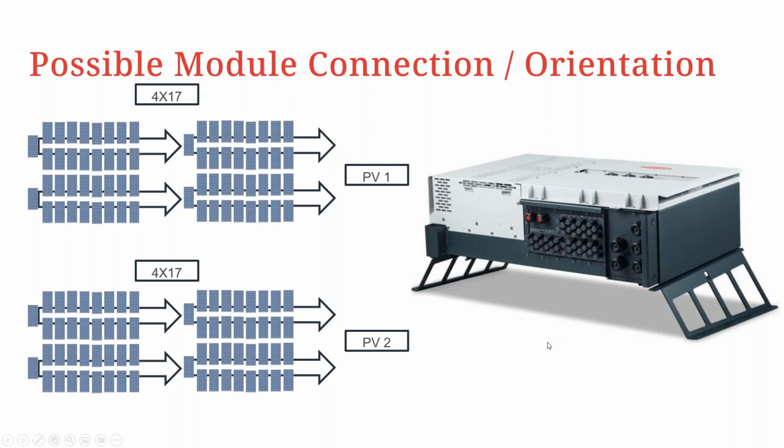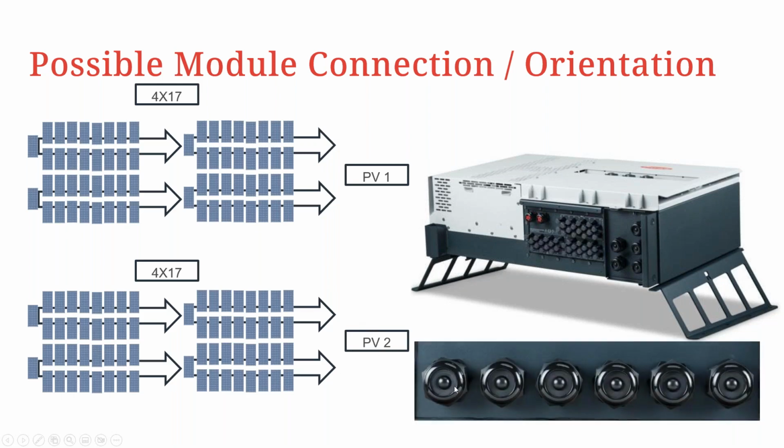If it is pre-combined, meaning that, for example, we have all these modules connected to one DC combiner box, and all these modules connected to another DC combiner box, you can have something like this. Because definitely if you're using DC combiner boxes, you're going to be coming out with larger diameter cables. So here we'll take this form, that is the input part of the inverter, the pre-combined version. We'll now have larger input terminals where you can come in conveniently with your larger diameter cables.